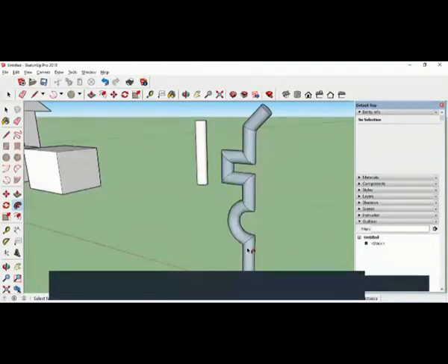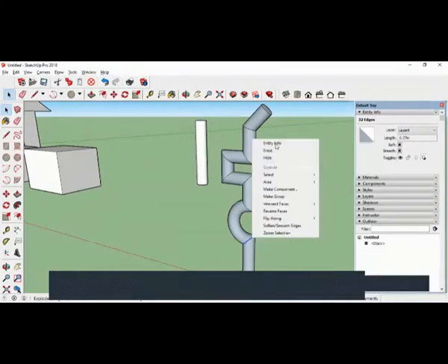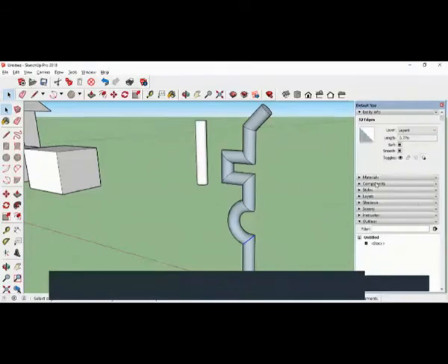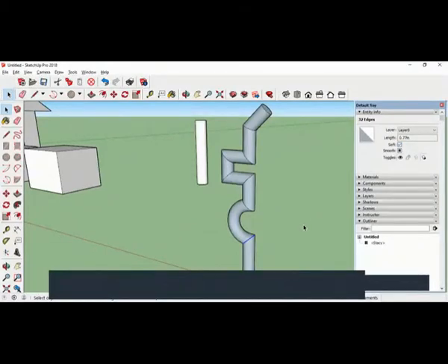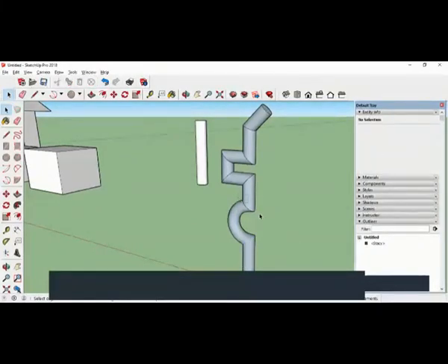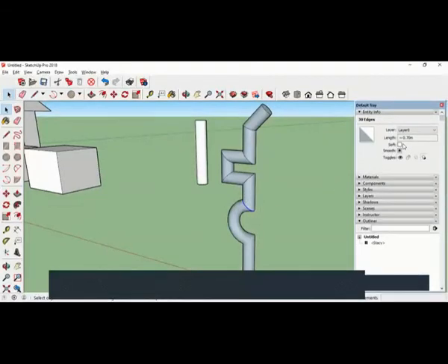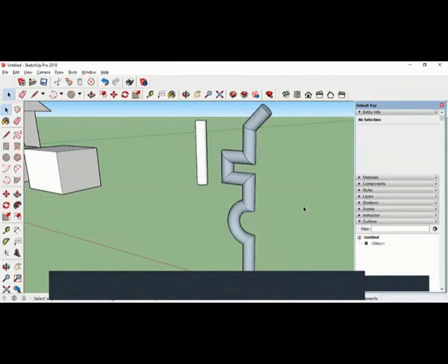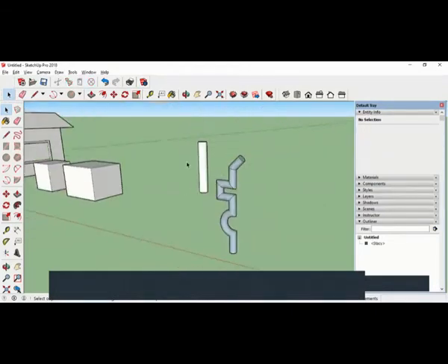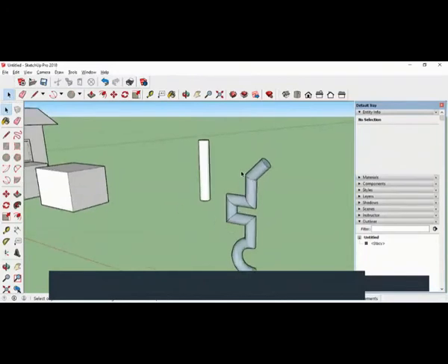Okay. We can remove these joint points. Cancel. You select this point. Okay, you selected only that one. So immediately you get an entity info here. If you don't get it here, right click, entity info. In the entity info, there is a soft button. Click that. So it has gone. Like that, you can remove one by one. That dot, if you want the line, select, remove.